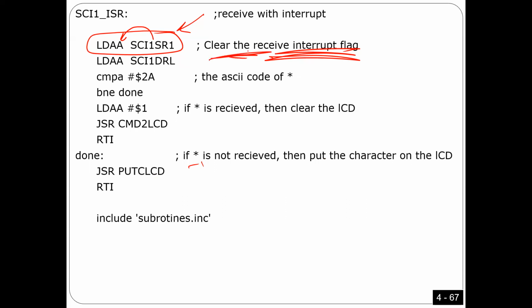Very important, as I mentioned many times. Please, if you do your capstone or any project, don't forget you have to clear the flag bit. Don't forget it. We did it right now. We did it in RTI, and the only exception was IRQ. I don't need to do it in IRQ. I'm going to do it in the timer shortly. Any questions, guys?